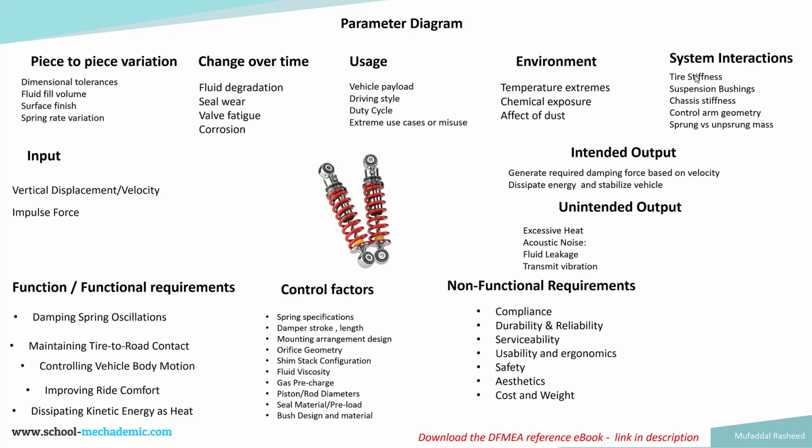So tire stiffness and the spring stiffness are basically in series, hence they perform overall for the vehicle dynamics of the vehicle. Suspension bushings also should work in unison with the damper bushings or shock absorber bushings, hence any change in that will cause change in the overall performance.